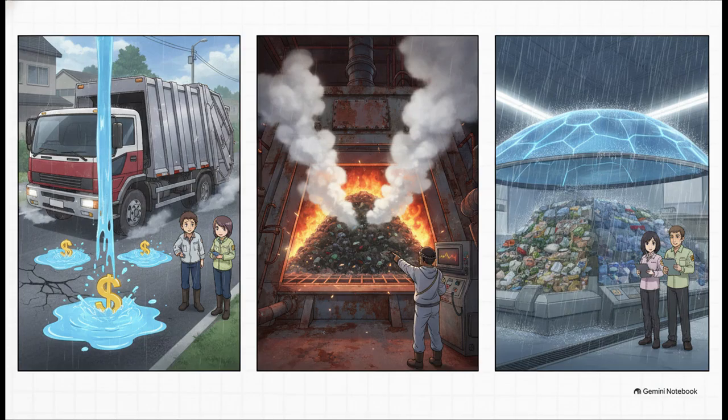So why does all this water matter? Honestly, it's an economic nightmare. Moisture increases the total weight, which instantly spikes transport costs. You're essentially paying good money to truck water around. On top of that, it completely ruins the economics of incineration. If the waste is too wet, the facility wastes precious, expensive energy just boiling off that water before the trash can even catch fire. This is exactly why you'll see waste transfer stations heavily insulated from rainfall.